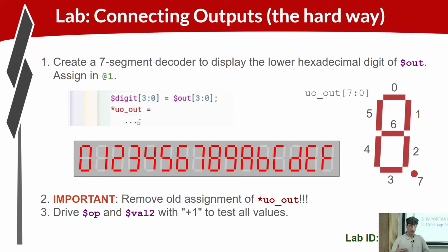So this expression is if the output value is a 0, drive the bit pattern that represents this 0 pattern, right? If the output value is a 1, drive this pattern. If the output value is a 2, drive this pattern, right? So what sort of structure are we going to need for that if-then-else case kind of structure, right? It's a mux, right? We're multiplexing all the possible input cases with the output values that they should have.